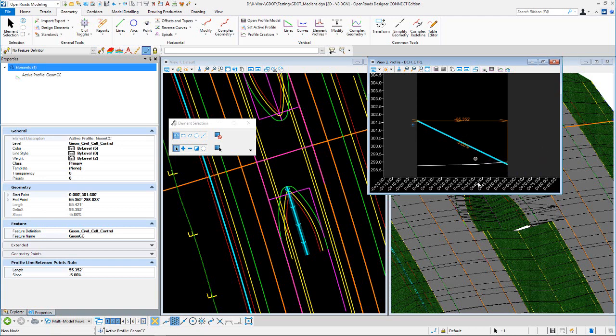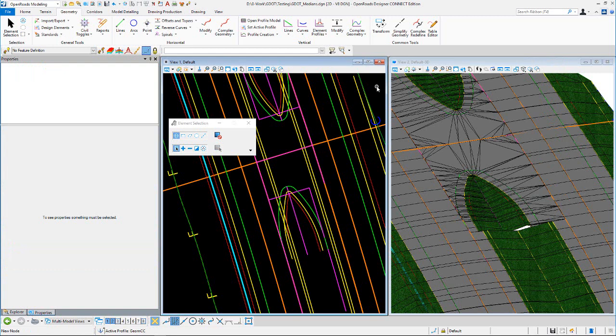And then what we're going to do after we come in and place your added lane, your turn lane, and your taper in your turn lane or storage lane, we're going to show you how to adjust this profile to meet this ditch over here. All right, but that'll be after we place our next cell, which is going to be the median turn lane cell.